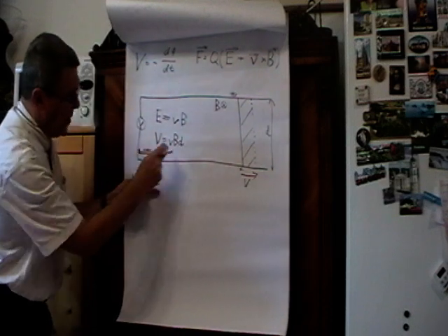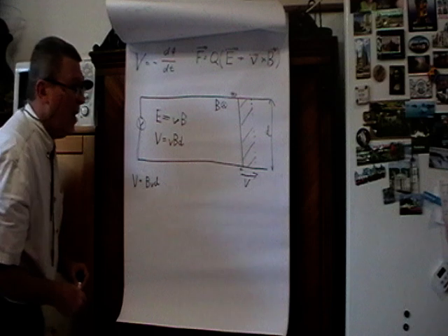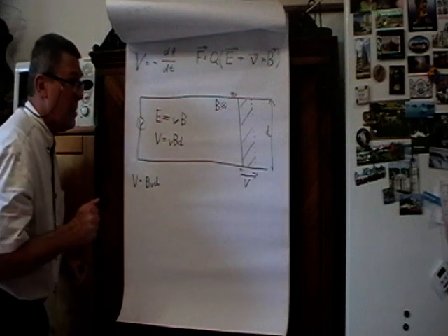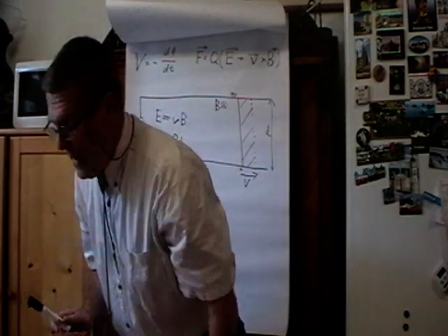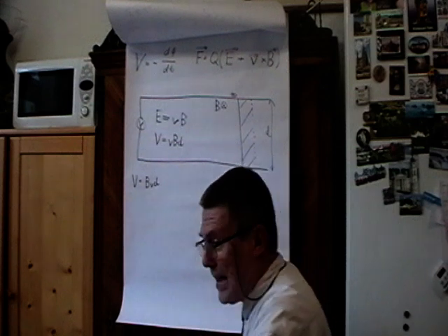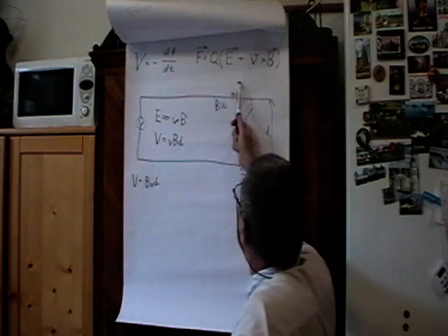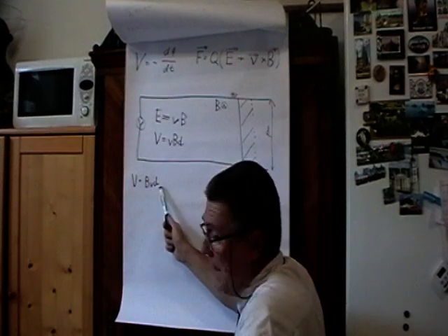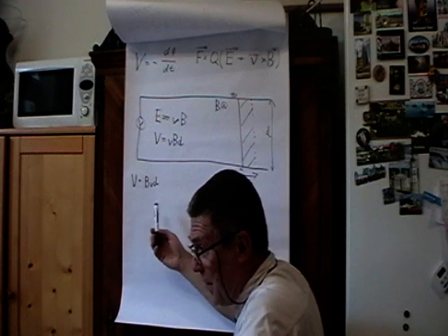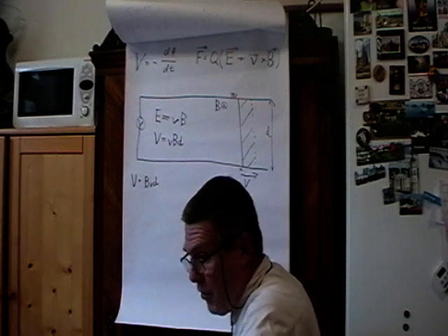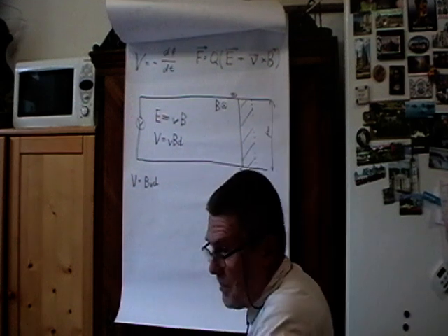Well, and you can easily check that we have obtained the same amount of voltage caused by moving that conductor within the magnetic field. Just now we can attribute this more specifically. We now know that in our experiment the total voltage over the loop is BVD, where B is the flux density of the magnetic field, V is the velocity of motion of the conductive stick, and D is the distance, the length of the stick.